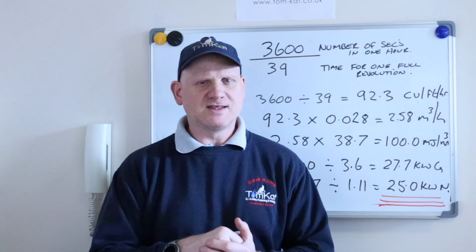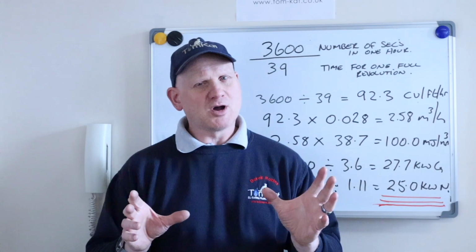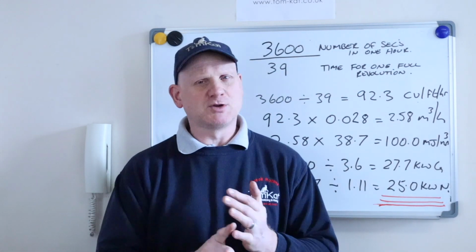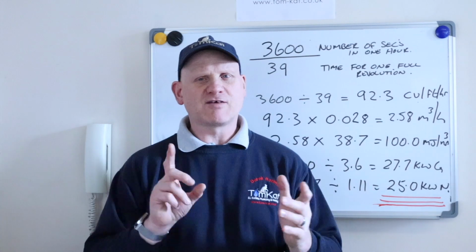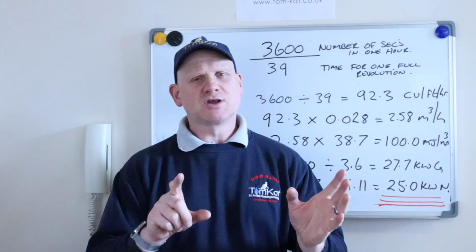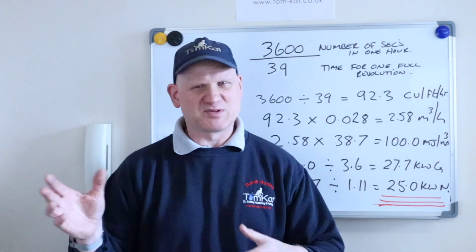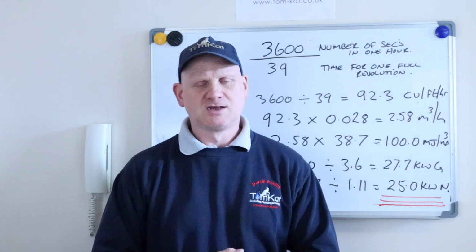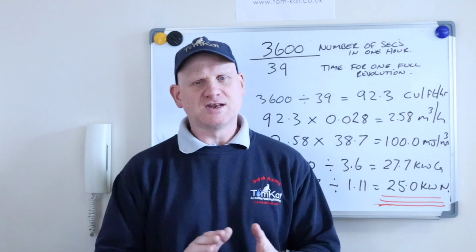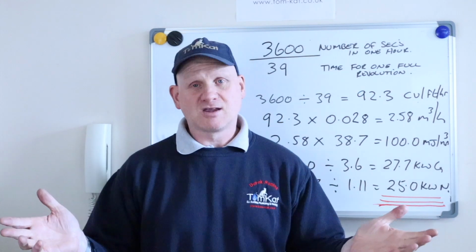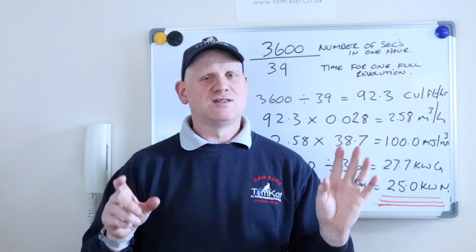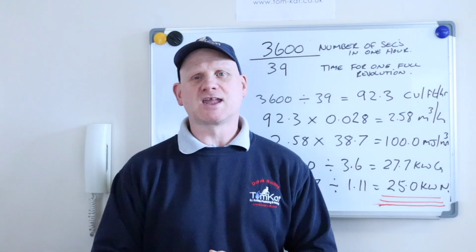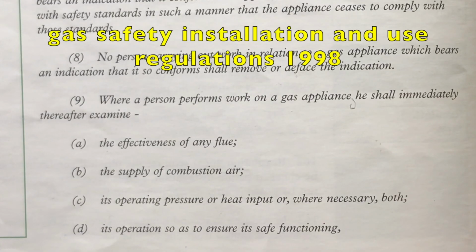Remember, we're gas rating the input. So when we're gas rating boilers, it's not as straightforward as if we're doing cookers or fires. Again, we have to make our engineer's judgment, because if we did do this 5% and 10%, we would be a million miles out, okay? So when we're gas rating condensing combi boilers, or any combi boiler that modulates, then we will need to make again our engineer's judgment.